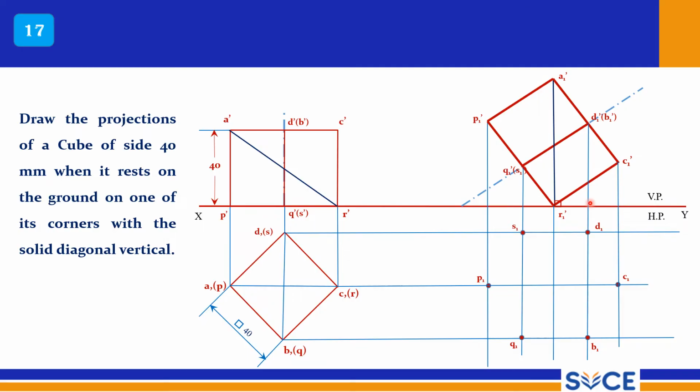All outermost points should be connected with thick lines. Now you see this is R, and AR is the diagonal. Both are lying at the same point. Now you have to decide which lines should be drawn thick. A is connected to D and A is connected to B, so these lines should be thick.